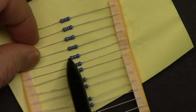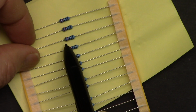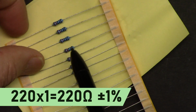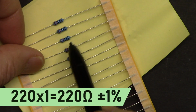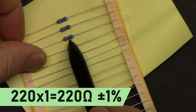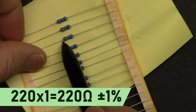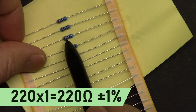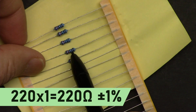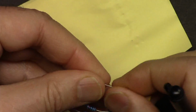This is a 220 ohm resistor. Now we have red, red, and then black: 2, 2, 0, because red means 2, red means 2, 2, 2, and then black. That black means a multiplier of 1. So 220 times 1 is 220, and then this is brown. If it is brown, then this is 1%, which means it has 1% tolerance.